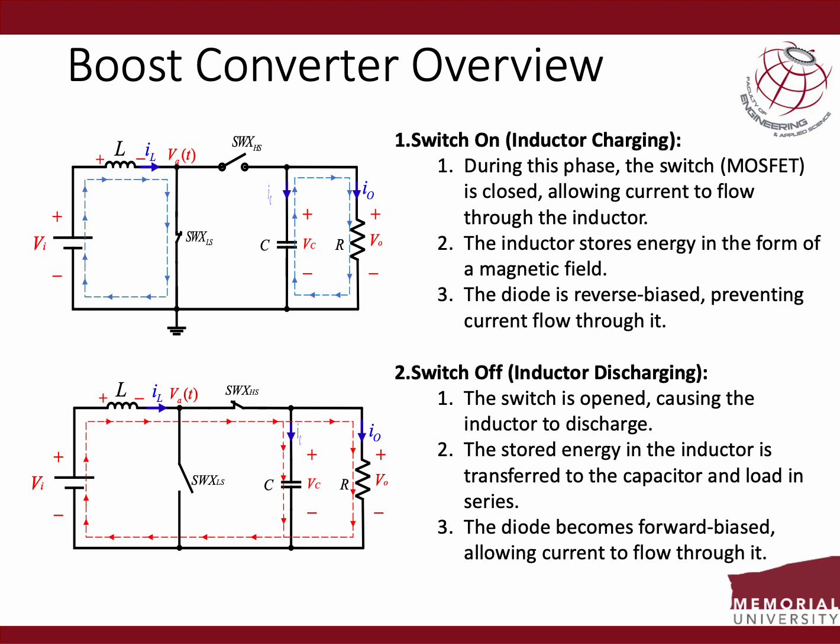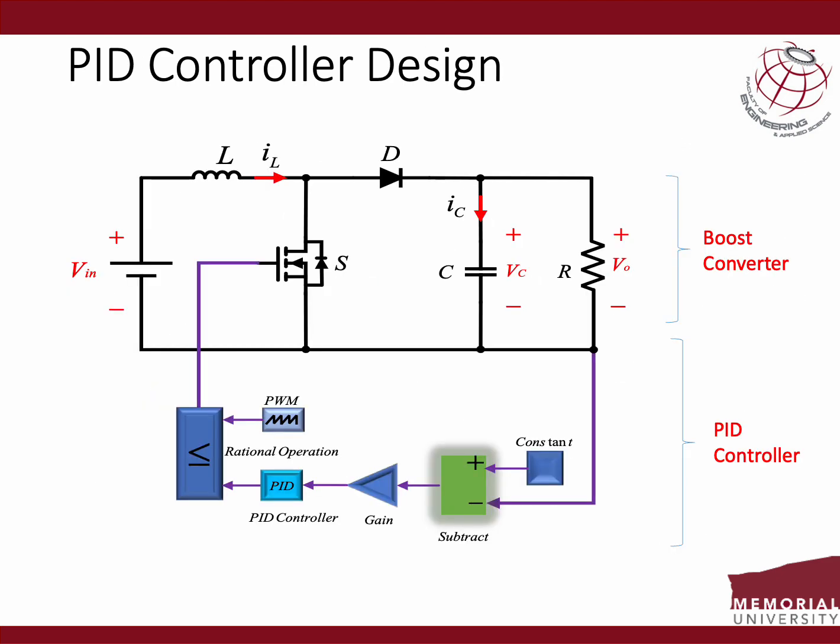So you realize that at the load side, V0 becomes VC plus the voltage from the inductor, VL. By so doing, we have a voltage magnitude greater than Vin, and this logic gives us a boost converter, because the output becomes more than the input.